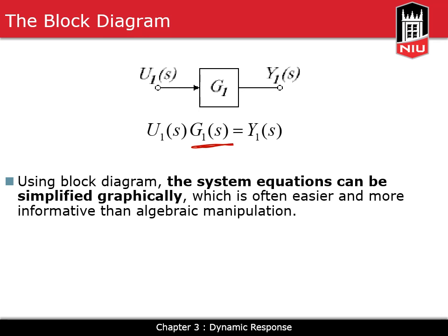If we wanted to work in the time domain and find y1 of t, then we would have had to find the convolution integral of u1 of t and g1 of t. We don't do that. Whenever we use the block diagrams, we work in the S domain. If we have to, at the end, we will do an inverse Laplace transform.